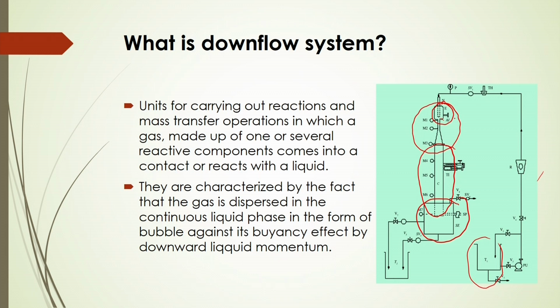The jet automatically sucks the gas and carries it along through the ejector, which has a throat section and a diverging section. If it plunges into a pool of liquid in the contactor, there will be a formation of gas bubbles suctioned by the liquid jet, and these gas bubbles are carried downward by the downward liquid movement.